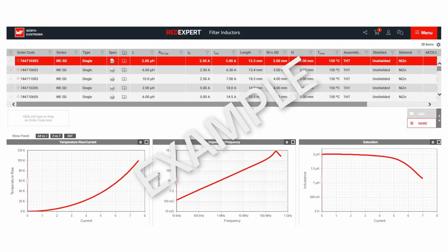All the data which you will find here is the same as in the data sheet, but because it's a measured value, you even have the possibility to see what happens when you put this device at minus degrees, like minus 40 degrees. How much is its inductance dropping? How much does its saturation move, especially in a very hot area? You may have some inductance operating above 100 degrees Celsius, and that means the inductor will saturate a little bit earlier. But how much earlier? No manufacturer tells you until today.